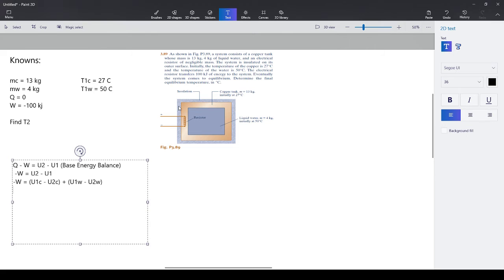So the liquid water gave away that it is liquid, therefore it's saturated liquid. We assume it's a saturated liquid because, remember, if it's liquid water, we use the liquid water values to approximate at a temperature, correct? So we just talked about that approximation. When you see something like that, that is another hint, meaning that it is liquid water and you use the liquid water table at the temperature, not the pressure. Okay? But yes, for this one we need specific heats.